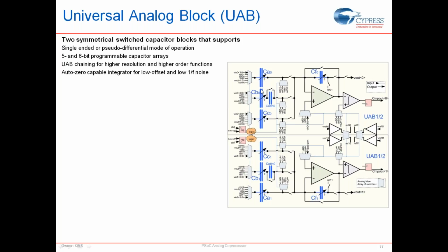So if you're implementing a difference and you also have an integrator implementation, then what you're implementing is kind of like a delta signal modulator. You're taking a delta and modulating it onto the integration capacitor, which is the feedback capacitor. By the nature of this whole thing, this is also a sampling circuit with the holding of that signal being your feedback capacitor. So now you've implemented a sample and hold circuit.